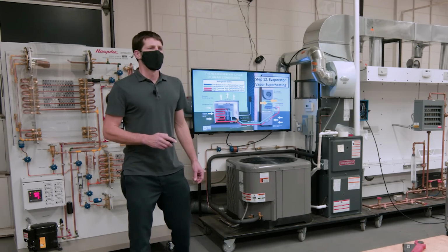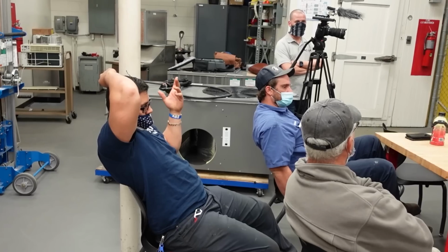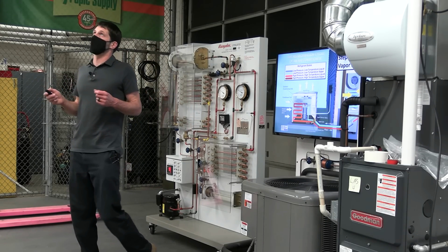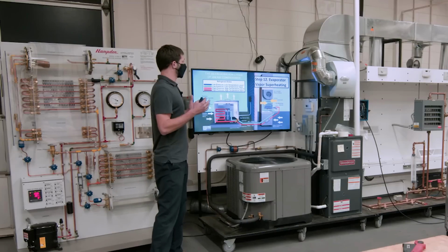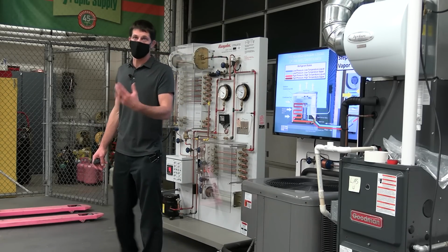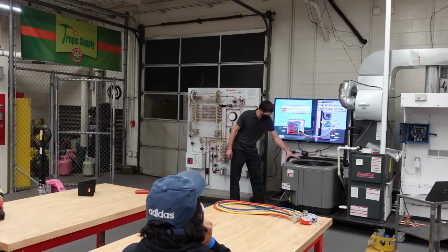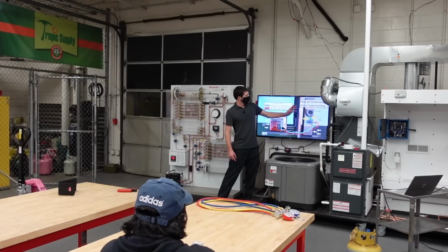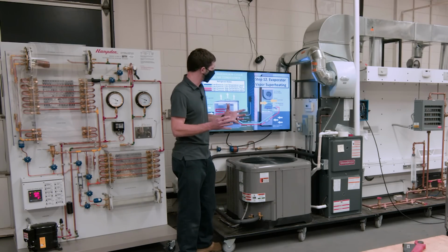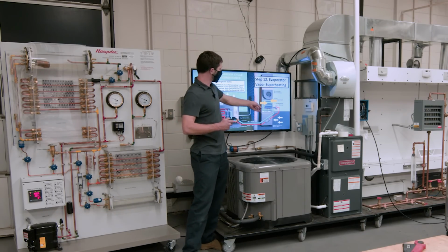You can never have 32 degrees saturation, because then you're going to freeze the moisture on the air, right? Yeah, on the evaporator. As long as you're above that, you're good, right? If you're above it, you're good, but you want to make sure that you have the correct amount of airflow. So you're thinking anywhere from 350 cubic feet per minute to 425 cubic feet per minute blowing across here for every 1 ton of air conditioning. Say this was a 2-ton unit, it's 24,000 BTUs, you're going to need roughly 800 CFMs, about 400 CFMs per ton, coming across this evaporator coil to have the correct amount of airflow. And that has to do with applying the heat to the outside of the coil for the refrigerant to absorb.